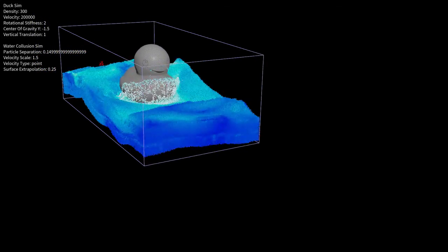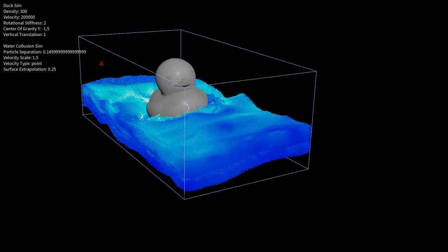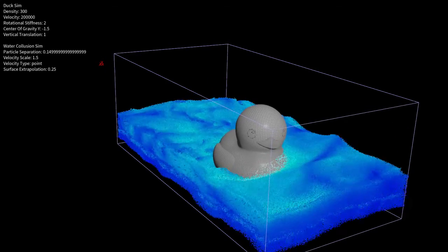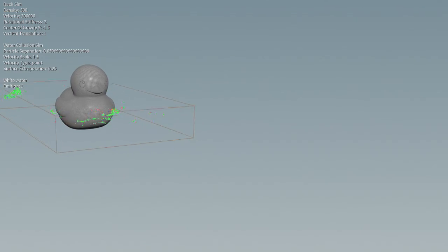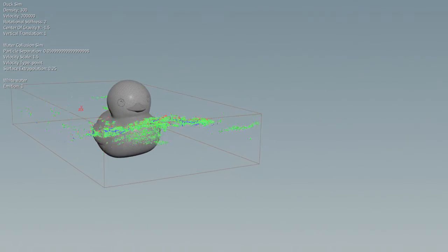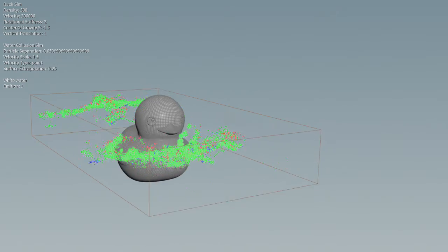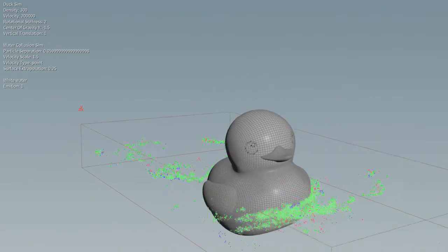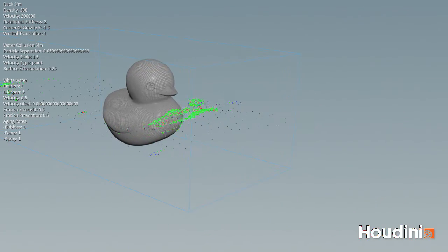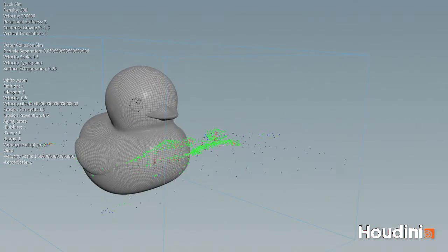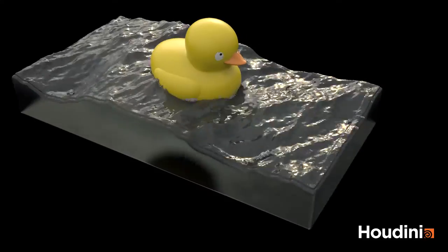And here I put all the parameters, I wrote these out on the left side of each of my little flip books here so that you can see what I'm doing. This is the whitewater simulation that I did. This is a little separate. It's simulating on the surface of the water using the acceleration of the particles to emit and figure out where it should be emitting. So I'm playing with it here on the left. You might be able to see foam, spray, bubbles, different aging amounts.